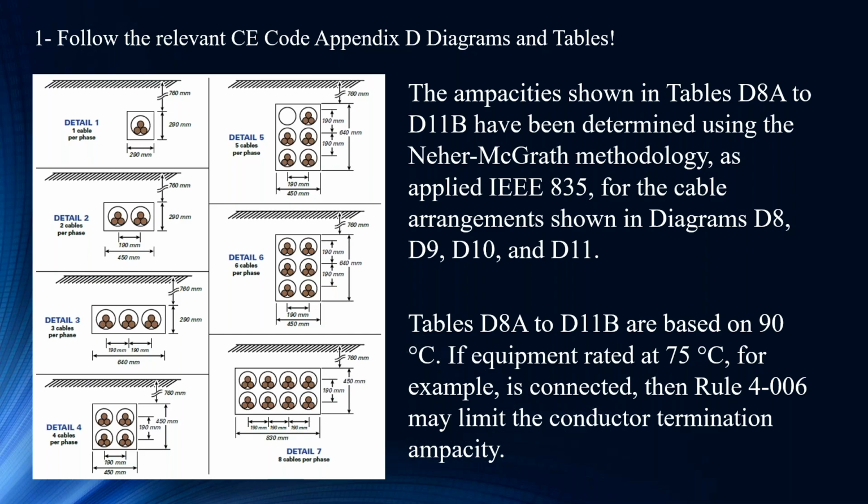So definitely this is going to reduce the ampacity by 5% to 8% below the tabulated values. After all these approximations are made, their variation from the actual value adds up, which may result in significant discrepancies and a wrongly sized cable.